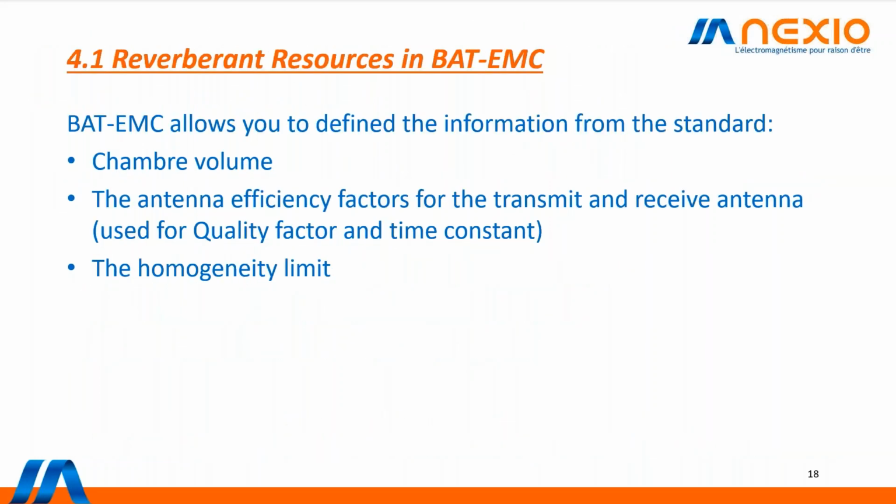So BAT-EMC will allow you to define the information from the standard: chamber volume, the antenna efficiency factors for the transmit and receive antenna, used for quality factor and time constant, and the homogeneity limit.